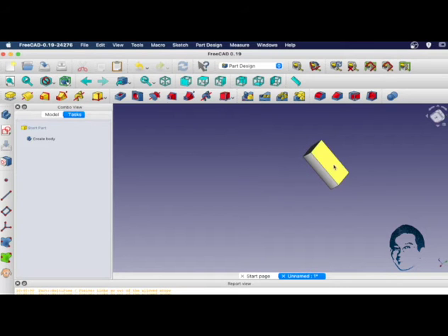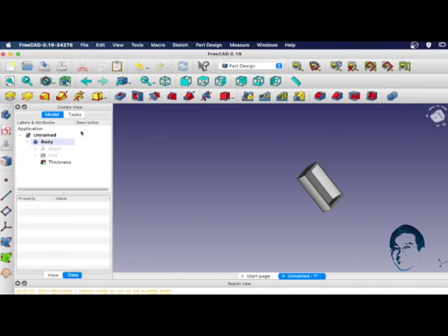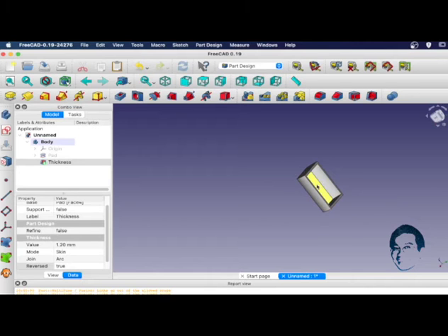Next, we're going to select this surface here and create a thickness using the thickness tool, to create a thickness of 1.2 mm and make the thickness inward, so that you keep to the original size that we have. Alright, click OK. The next one is to create two cylinders inside here, which is the pivoting leg for the switches. Alright, click on this surface.